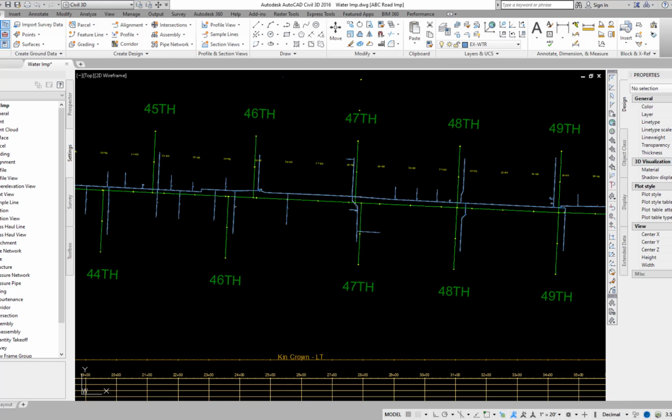Where any portion of the water line is at an elevation that is greater than 30 feet below the crest, combination air and vacuum valves should be installed at the crest. If a break in the water line should occur, this will allow air to inflow into the water line and eliminate negative water pressures to the extent that they could damage the water pipe.